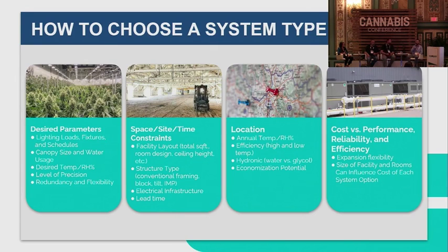I think in addition to that, Troy, you often find that different municipalities will have screening requirements for roof or sidewalk view that can play a huge factor, whether you're going to do a packaged unit or a chilled water piping system. Yeah, so in that case, if I've got some of these site restrictions that won't let me put it on the side, and I don't want to pay for a structural upgrade, even though I'm concerned about CapEx, overall impact to my project, is a packaged DX system at that point my lowest CapEx?